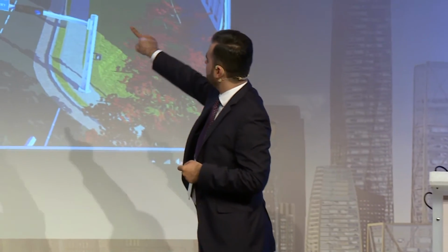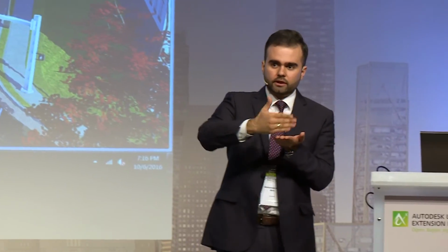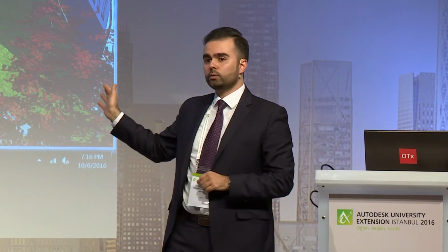Quantification is in Civil 3D, to be honest, for rail. We have quantification, but for the roads. So if you're designing any road on the fly, if I click here and I sketch the road, on the right-hand side, it will give me directly the cut and fill. It will give me the cross sections. It will show me the super elevation and everything. For roads, it's a complete solution. But for rail, no. We just sketch the rail. We use the rail layout module inside of Civil 3D to do all of the design, taking into account, for example, the cant and the switches, etc., and the quantification. So it's done in Civil 3D.